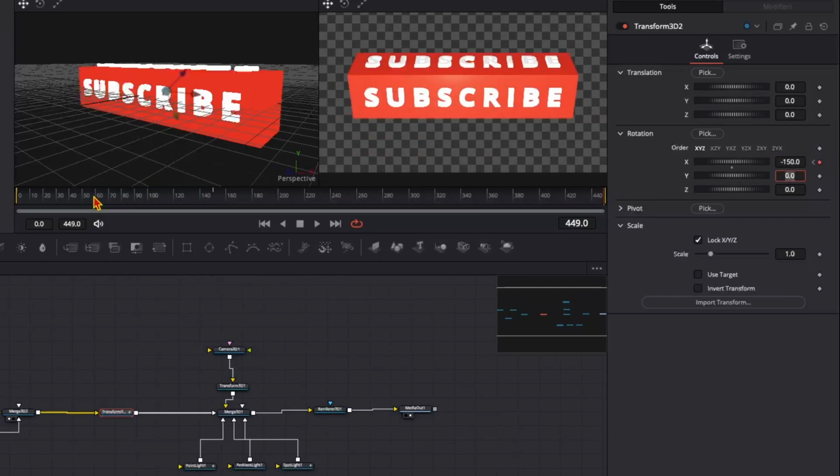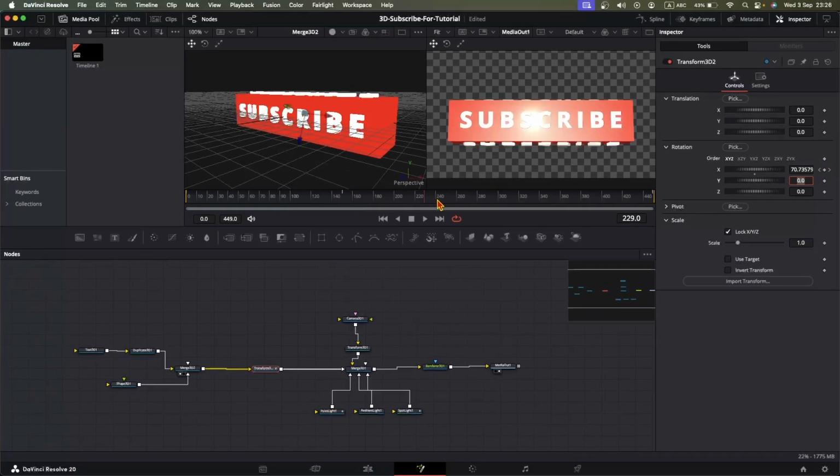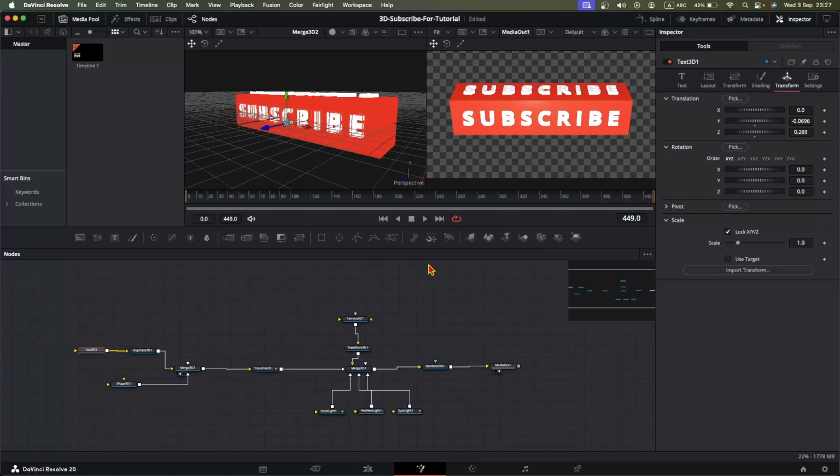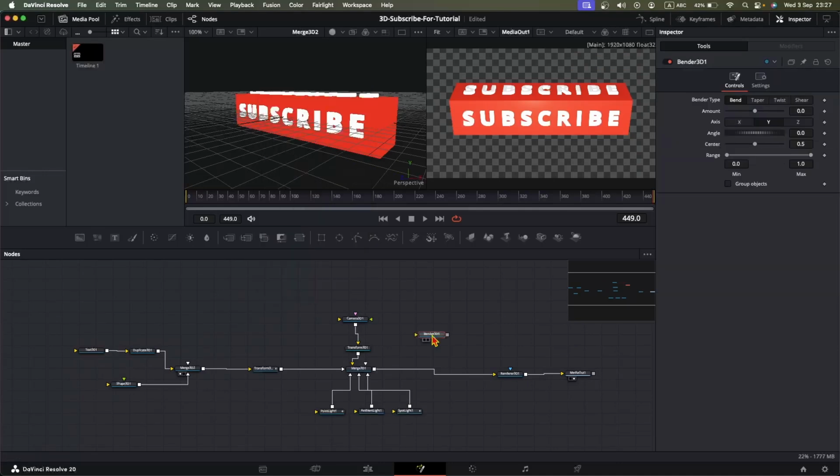Now we have a full rotation in one side and from this frame it starts to rotate back on the X axis until it reaches minus 150. So we have one rotation here. Now since we have this animation, we have to also add the bender node. So we will add the bender node after the merge 3D node here, shift space, bender 3D node, and shift hold it, release it in between the render 3D node and the merge 3D node.